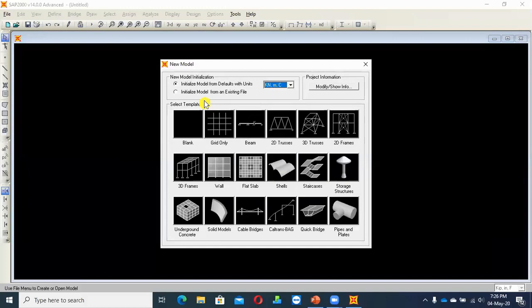This is very important, whether you are adding meters or millimeters or maybe newtons or kilonewtons, that makes a huge difference. If you're going for CGS units, the values that you add in CGS units, you'll not get accurate results unless you use CGS units here. So you have to be very particular on this. You have to be very confident on the unit that you use. So we are selecting the unit here.